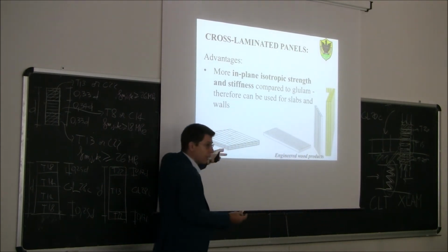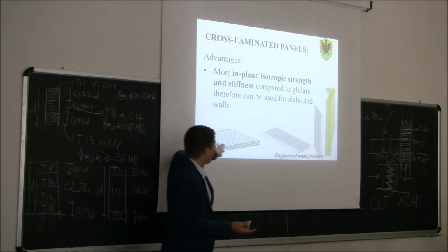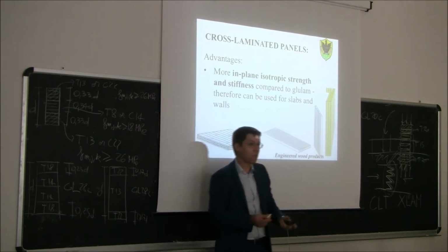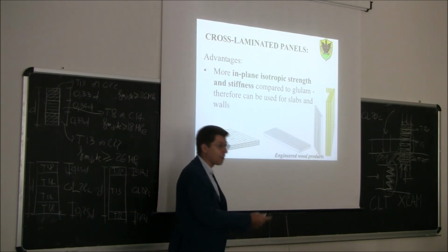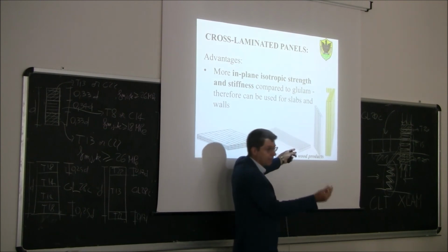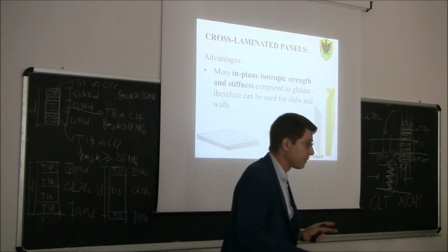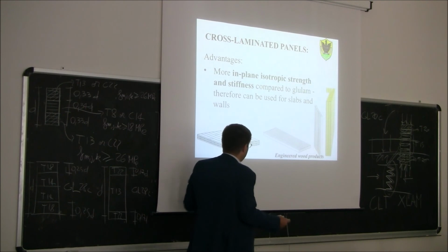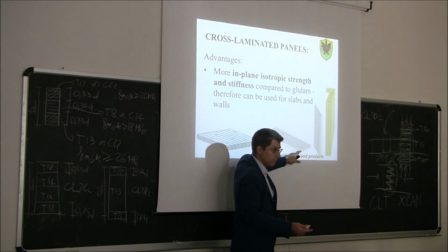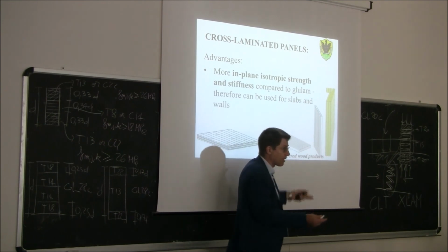Now, on the other side, we said the realistic cross-section is 2/5. And here, what would be the realistic cross-section? Let's say almost 0, because we are talking about bending in the wrong direction. Bending in the wrong direction means compression perpendicular to the grain, where we can get something, and tension perpendicular to the grain, where we can get nothing, basically. Okay? So in this respect, this material is highly anisotropic, I would say, because there is definitely a best direction, and another one where the strength is almost 0.